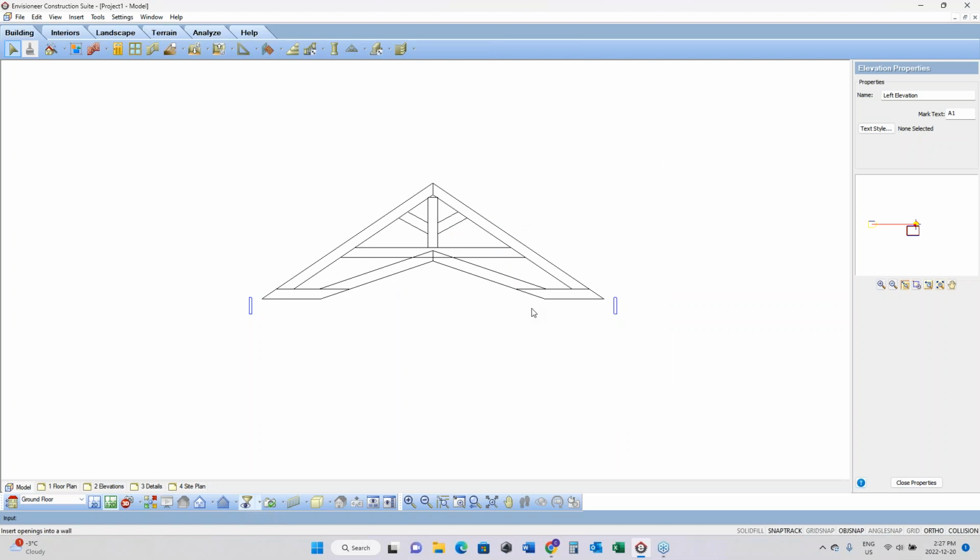Okay, so you can automatically frame a roof with rafters by turning all of the properties on and changing all of the sizes that I showed you today. So we looked at inserting the rafters and putting in the fascia boards. We put in some battens and purlins, and we put in some gable end framing to show you how you could put all of those in. Then we erased all of that away, turned off everything but our fascia boards, and we looked at creating a truss run all the way through our building, inserting a truss.